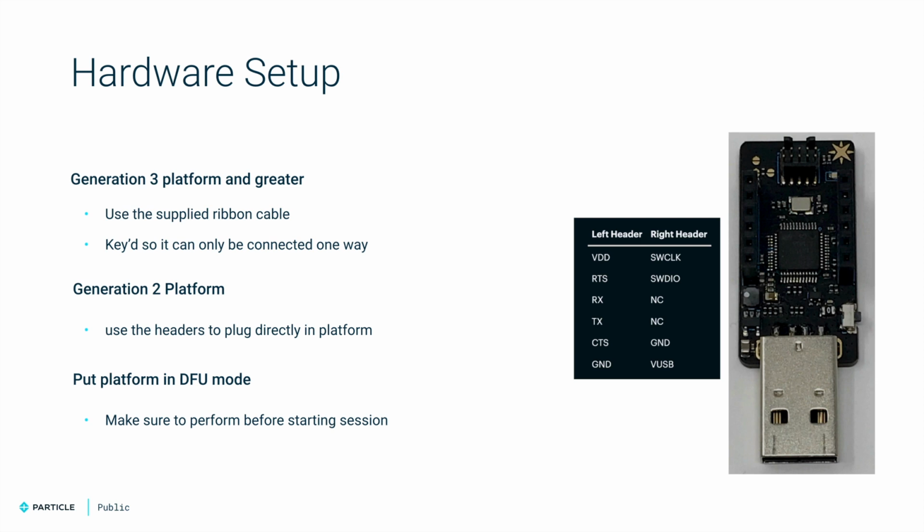Also, we typically recommend that you put the particle device into DFU mode before starting a debugging session, as it creates a known starting point for flashing firmware. It's that simple, and your particle device and debugger are now set up to start a debugging session.